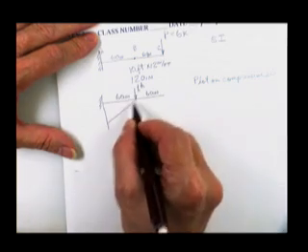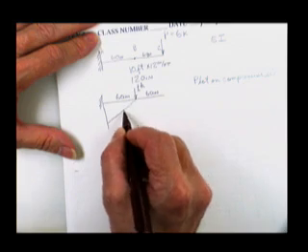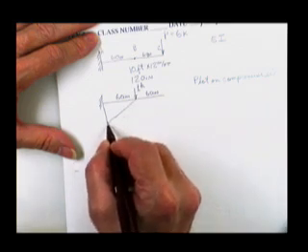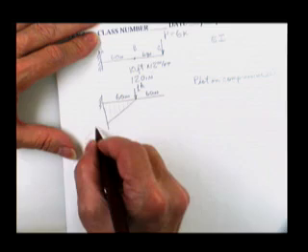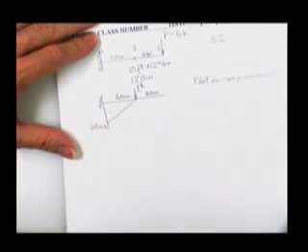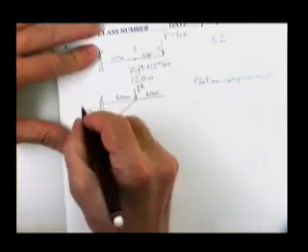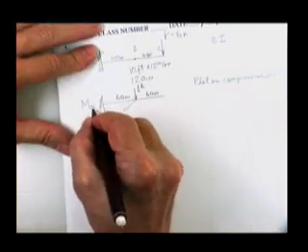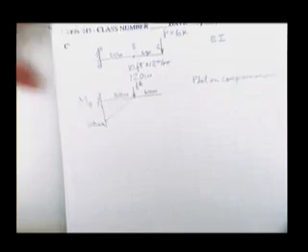The moment here is 0. The moment here is 1 times 1 inch, 1 times 2 inches, 1 times 8 inches, 1 times 40 inches, 1 times 60 inches. The magnitude of the moment is 1 times 60, 60 inch-kips. His name is M sub Q. A lot of books call him little m. I kind of like that better, but this is a great book, so it's not worth throwing away the book.